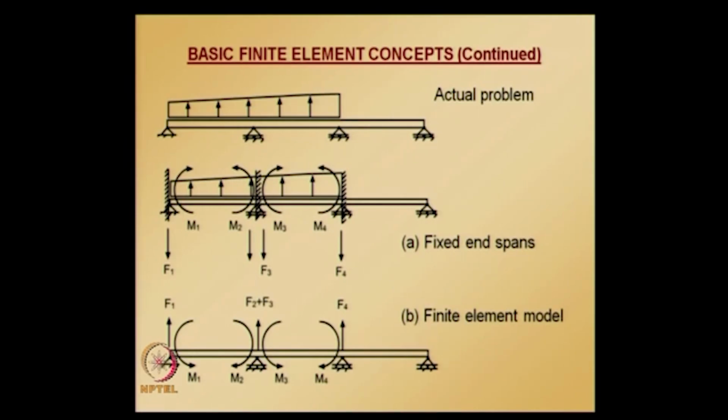and regardless of the actual supports, in the first problem the element ends are assumed to be fixed against any displacement or rotation. Such a structure will experience moments and shears in the loaded span alone, and that is, each loaded span is an independent fixed end beam. Exact solutions for these fixed end beam problems are easily available in elementary mechanics of materials books.